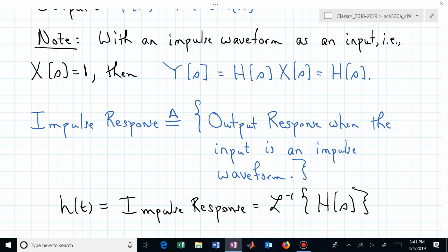And then you no longer apply an input, it's already energized everything, and then everything just starts exponentially decaying with an RLC circuit. That's what h of t is doing. It's showing you how the system decays after it gets excited. Its energy storage devices are energized.